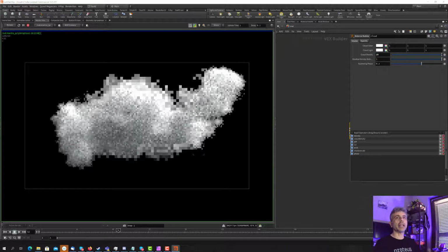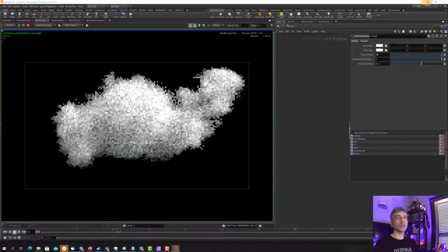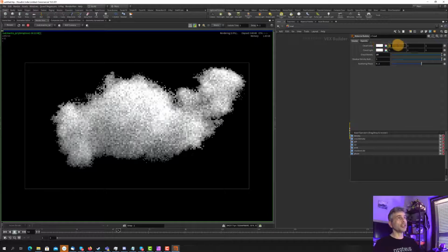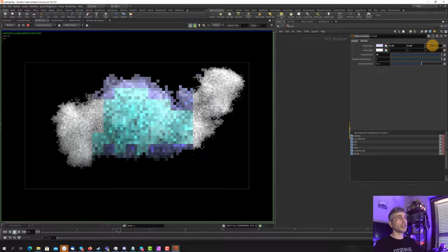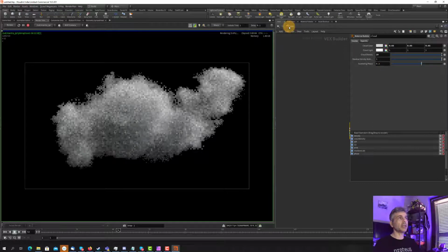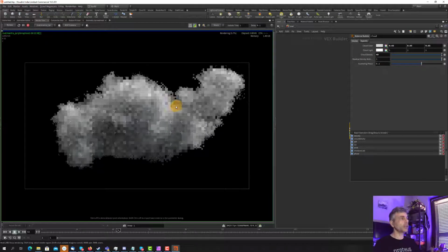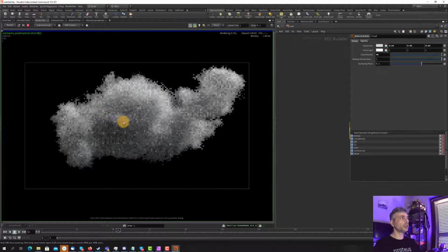Inside the limits, if we say that we have 50 limits for the volume, we have more bouncing inside the volume rendering. 50 maybe it's too much because, you know, everything is too bright, but having a little bit higher volume limits can give us a higher quality for our rendering. You see that obviously everything works together with the cloud color and the cloud density.